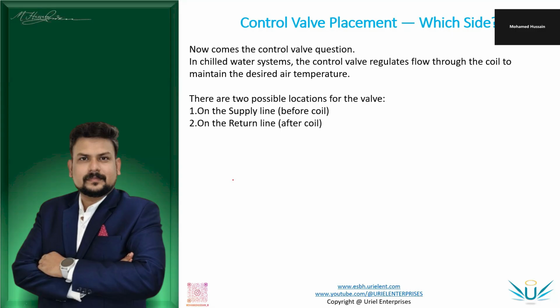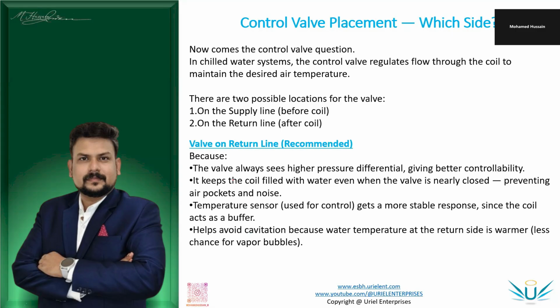Actually, most of the time the recommended practice is that the valve has to be placed in the return line. It is very important at design time also, when you are preparing the control submittal. In that control submittal, we showcase the flow diagram of the cooling coil, showing whether the valve is placed in the supply line or return line.